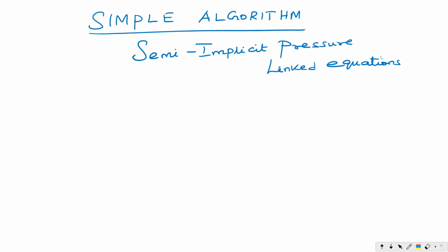That is the meaning of SIMPLE. This is mostly applicable or needed for incompressible flows. A flow in which the density remains constant, or the density cannot vary, is known as incompressible flow.